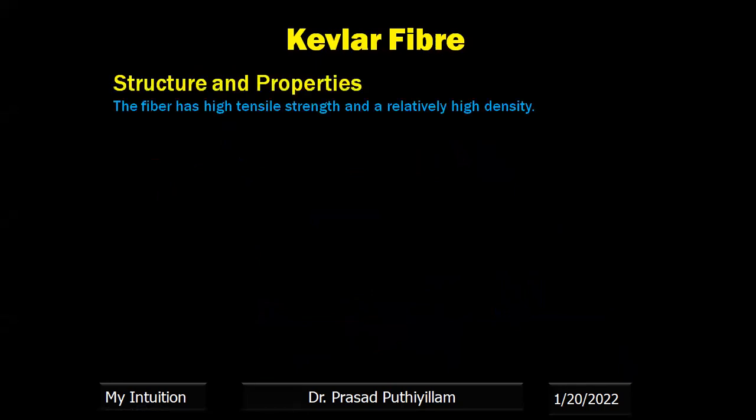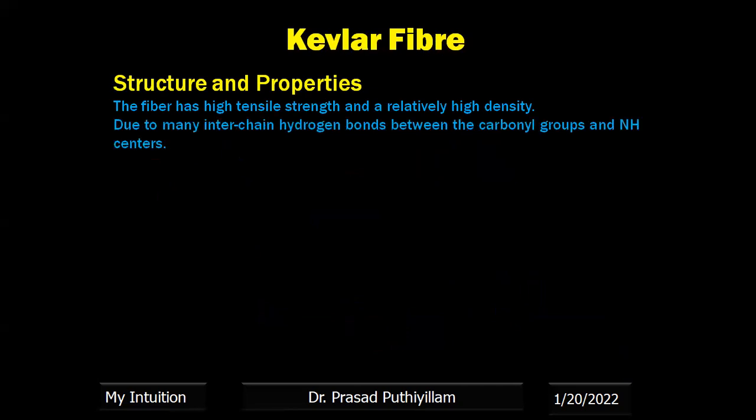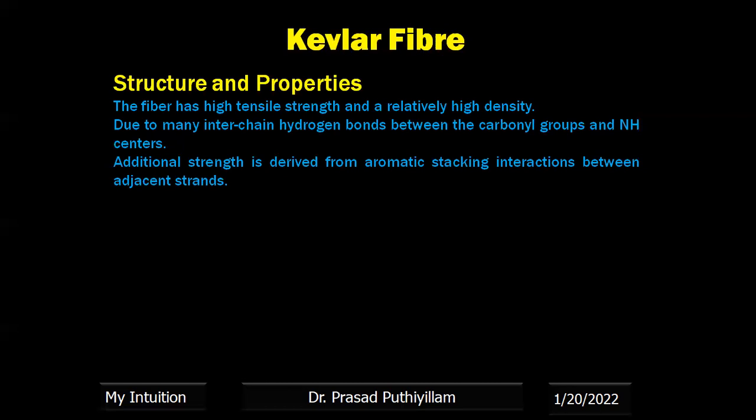Now, structure and properties. The fiber has a high tensile strength and a relatively high density due to many interchain hydrogen bonds between the carbonyl groups and the NHs. I'll explain in detail. Additional strength is derived from aromatic stacking interaction between adjacent strands. That also I can explain.